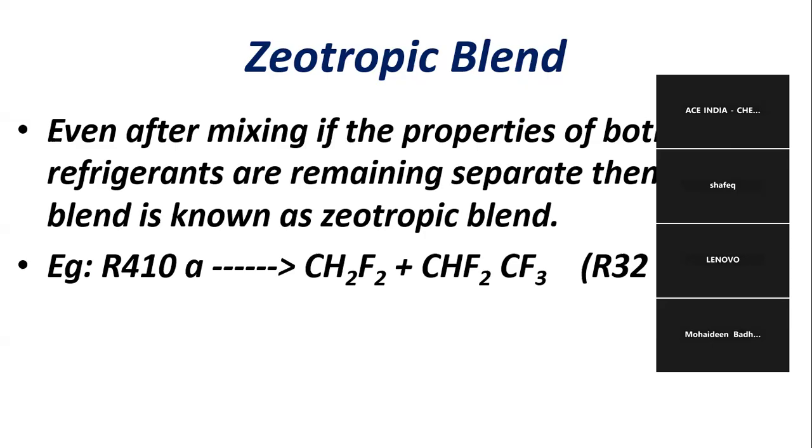That's for a normal technician, isn't it? But in the case of a blend, azeotropic or zeotropic, if the quantity is even 100 grams less than the normal situation, it is not advised to refill it. Instead, you need to entirely discharge the gas from the system and fill the gas again in a proper manner. If you refill along with the existing gas, what will happen? Eventually the mixing composition will differ, isn't it? So that's why it is advised, especially for blends, that even if only a little quantity is required, you should discharge the entire refrigerant and then charge it again initially.